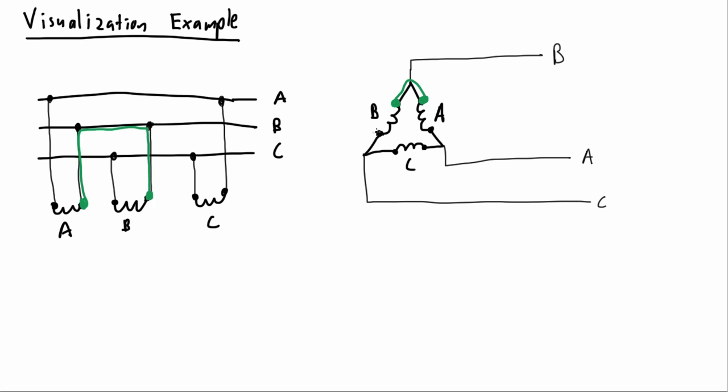And let's now do the leg from B to C. So this inductor connection point to that inductor connection point runs like that on the delta diagram. And on our 3-line, we start here and end here. So we can make the connection along this C line there. And finally, we'll finish up this C connection point here to the A connection point here. We'll make that in blue, so that little leg starts here, it's the C inductor connection point, and finishes at the A inductor connection point.